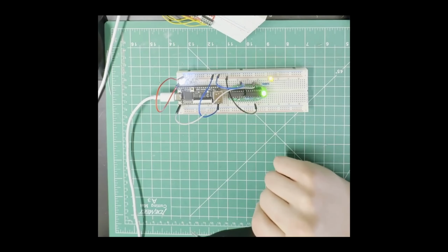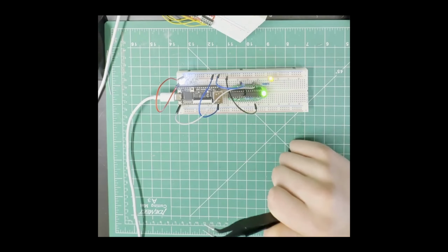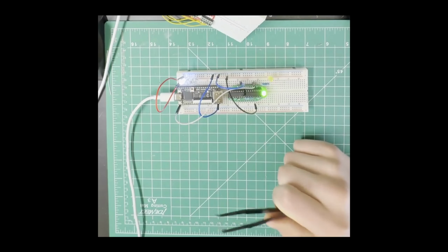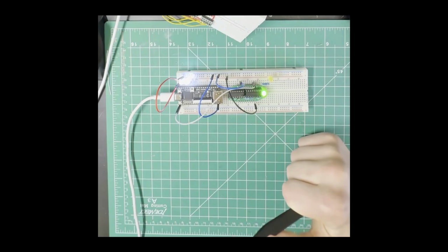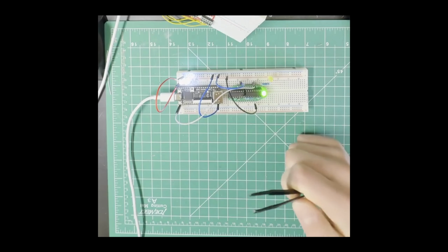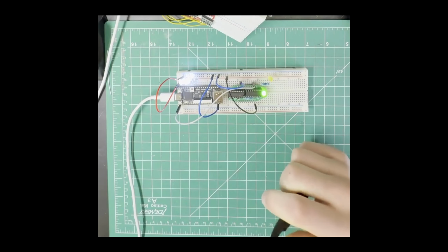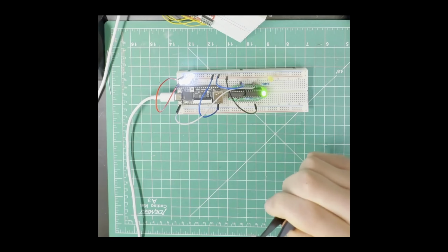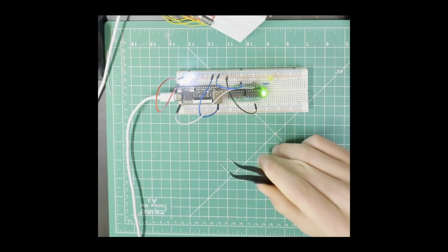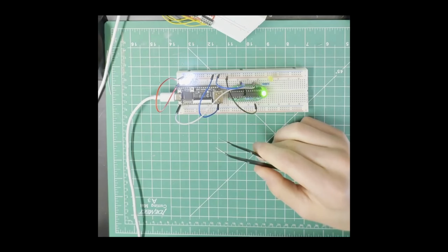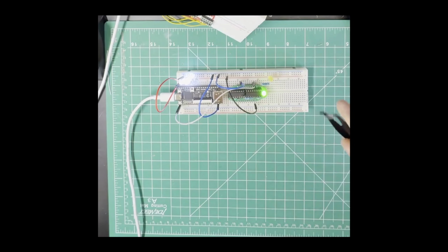And my Verilog program consists of about 500 lines of code. Most of that is basically just describing the instructions. My thing has 16 instructions, including the no operation, so really 15 usable instructions. And most of those instructions are actually just ALU instructions. So we have just add, subtract, and, or, not, XOR, all that stuff.